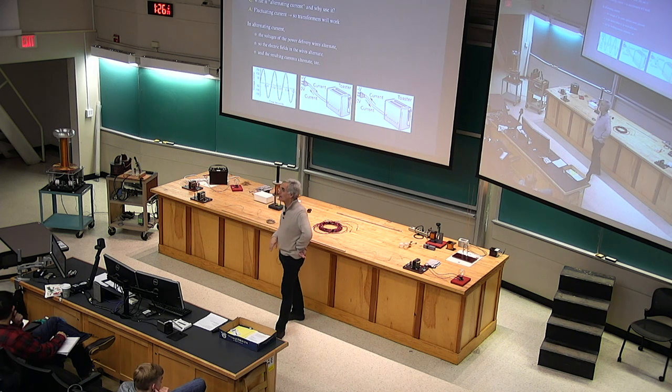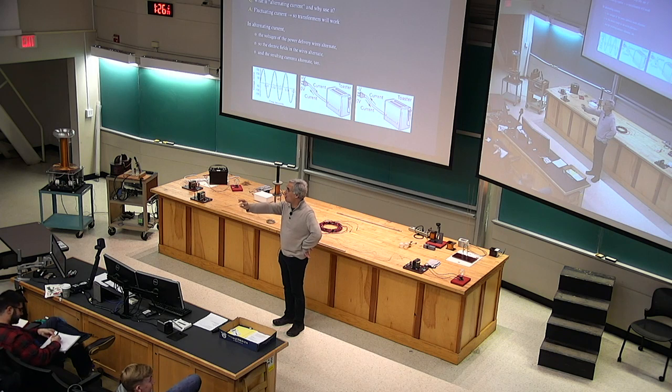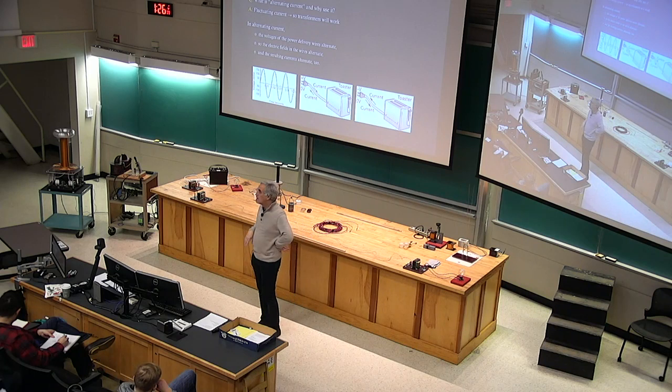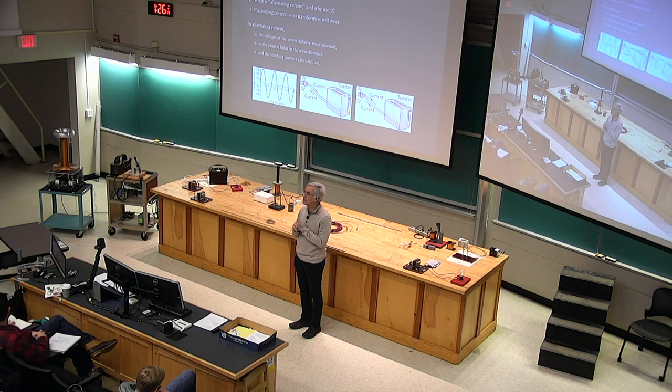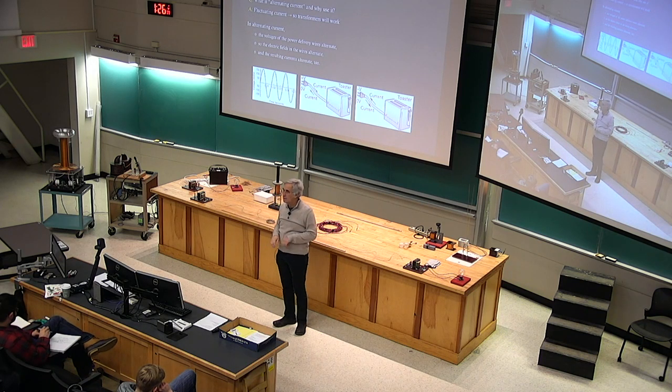Okay. In any case, you pay attention to those wires, because if you touch the white one, you're touching something that's typically at 0 volts. And if you then touch a pipe or the bathtub water or something like that, you're probably fine, because there's almost no voltage difference between the two. There's almost no electric field in you to push charges through. Don't touch black and do the same thing. Much more nasty. I mean, it bites, okay? Because now there's big voltage difference between it and sort of everything in your environment. Okay?